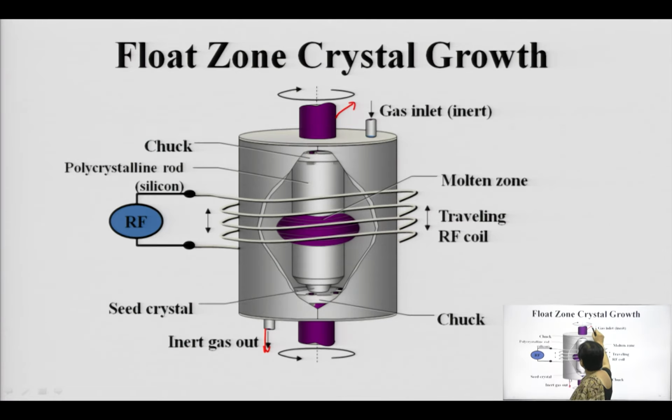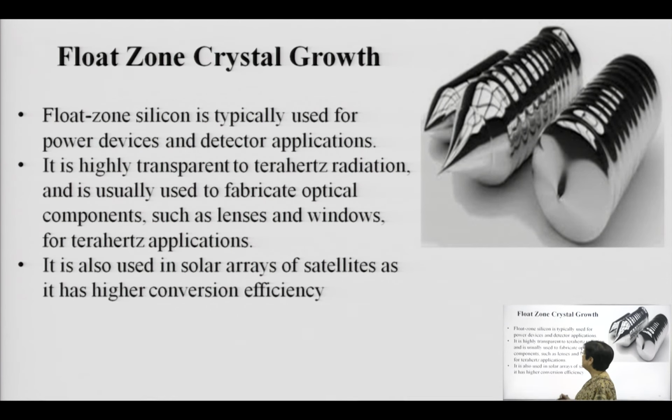The ingot is the same, and the seed crystal is of the same orientation, or it is basically the product which is deciding the growth rate. Apart from the localization in the heating used for melting the silicon, most of the other parameters or mathematical analogies are almost the same. The only thing is, since the crucible is not being used, there has to be a lot of precision involved in pulling the seed crystal, because the area is confined.